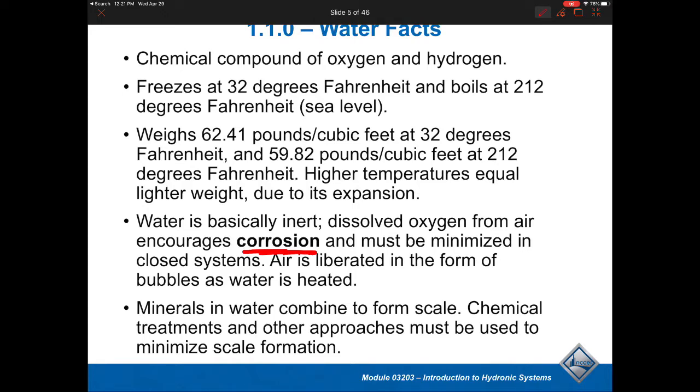And of course, another characteristic of water is that it contains minerals that can also lead to scale. In a closed loop system, I don't typically expect this to be an issue. However, in some systems where enough is leaking out, you will show signs of significant corrosion effects, especially when you're replacing all of that fluid.